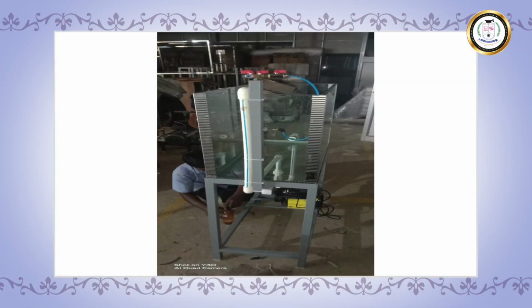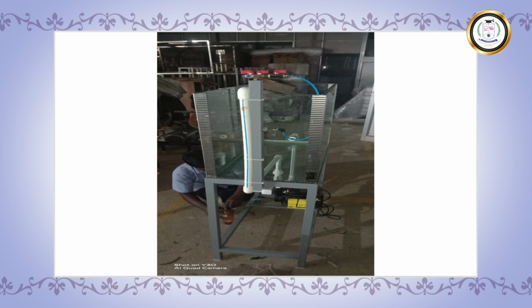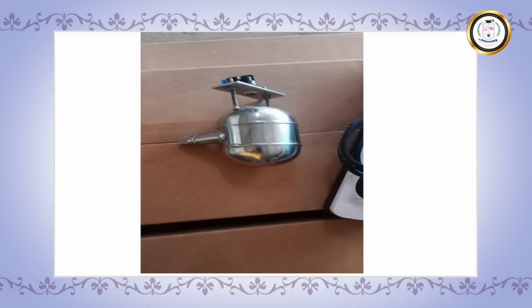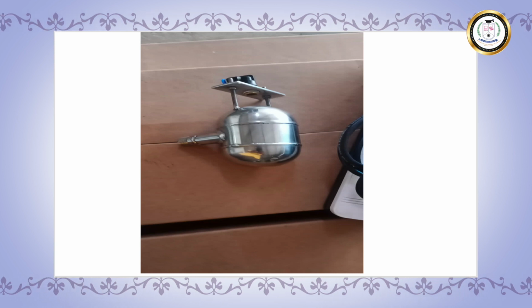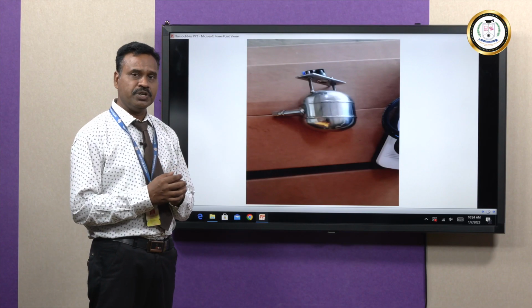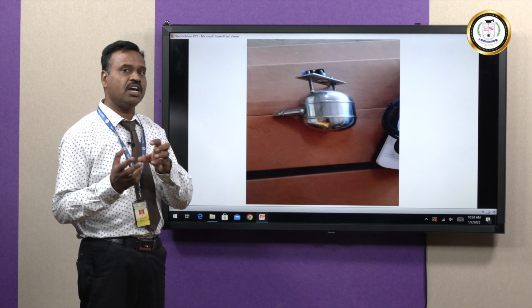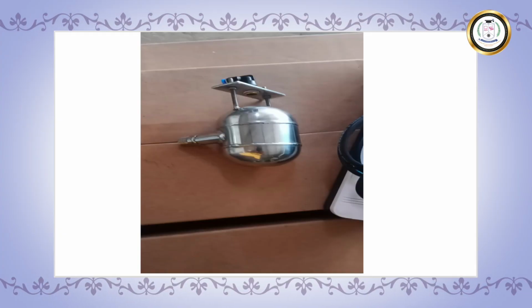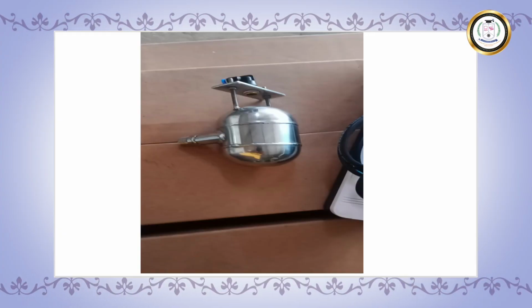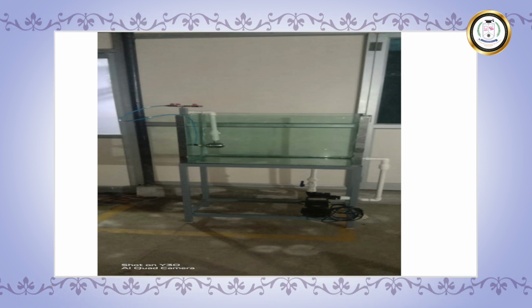This is the side view of this experimental setup, that is the micro nanobubble generator. This is the main device, which is a stainless steel vessel which possesses a nozzle inside. Whatever gas we are introducing, the splitting of the gas, which creates the shearing action between the gas and the water, can be achieved by means of these diamond-shaped nozzles which are enclosed in this vessel, that is the SS vessel. Okay, so this is the complete view of this experimental setup.